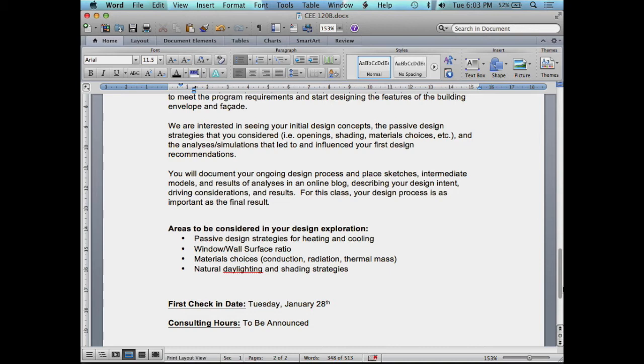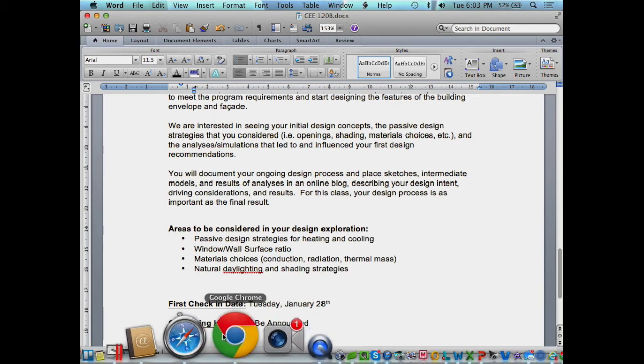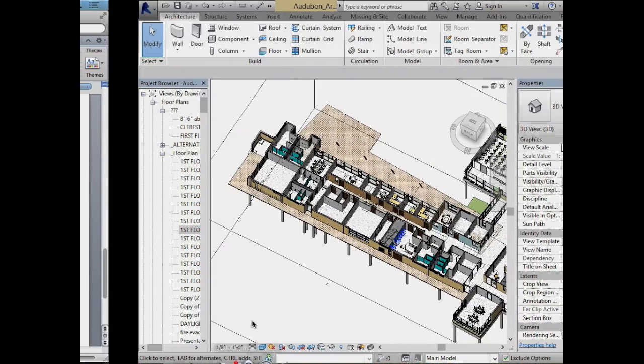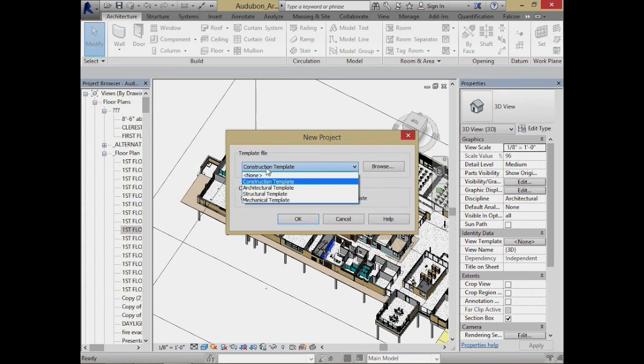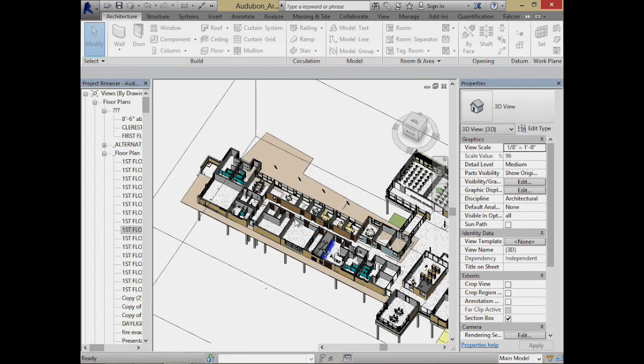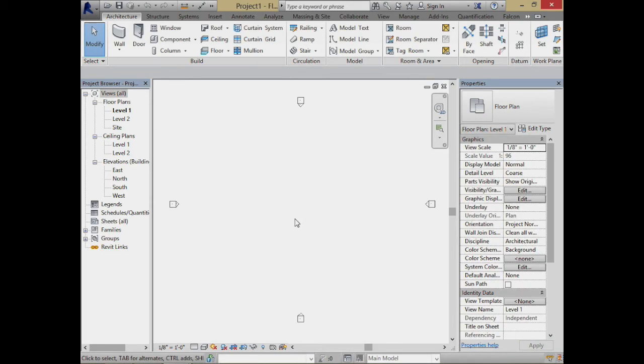So for example, even in a tool like Revit, let's go ahead and do this. I'll go back over there. Just open up a new file. Start with the architectural template. Okay, so let's start at the highest level. You need to create a building that's somewhere around 3,500 to 4,000 square feet. Okay, so that's a good starting point.